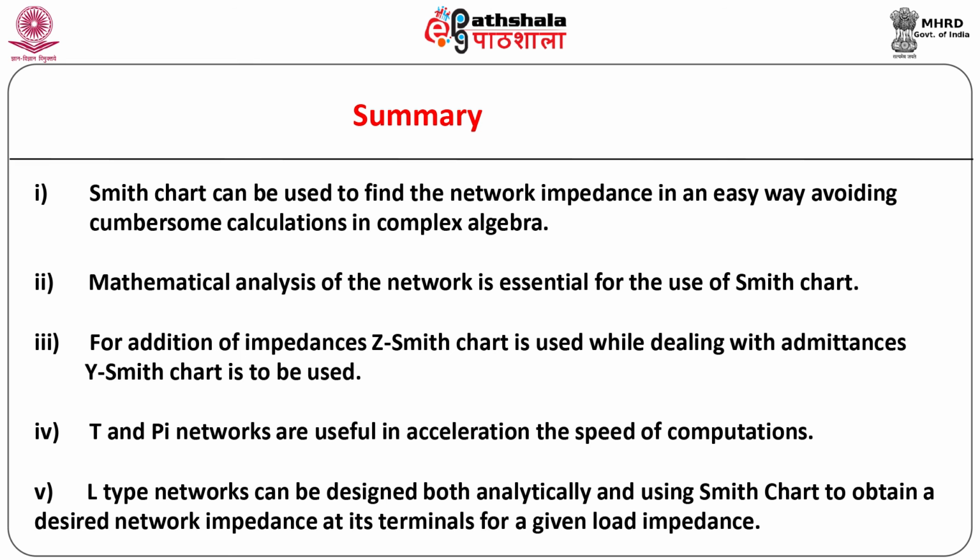The power measurement and the losses related to it in terms of dB can also be measured from the horizontal scales. The magnitude of reflection coefficient, transmission coefficient, VSWR, etc. can be measured from the set of 4 horizontal lines. In general, various portions of the Smith chart should be understood first.